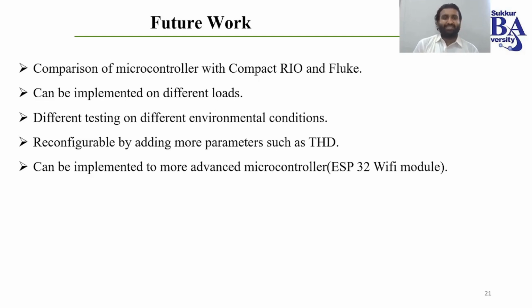Like we used just a resistor load, but we can replace it. We can add another reactive load, an inductor load, like a motor or something else. Then different testing in different environmental conditions: we can implement our PMU in grid stations and monitor how it behaves in different conditions. It's also reconfigurable by adding more parameters such as THD, and it can be implemented on a more advanced microcontroller like the ESP32 Wi-Fi module.